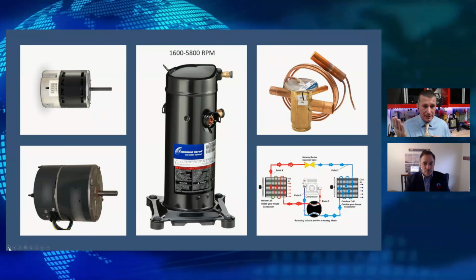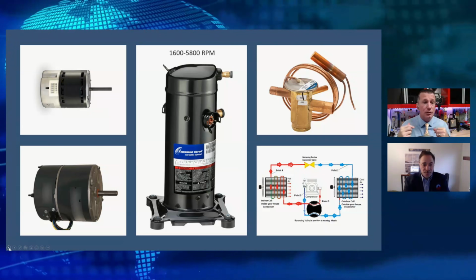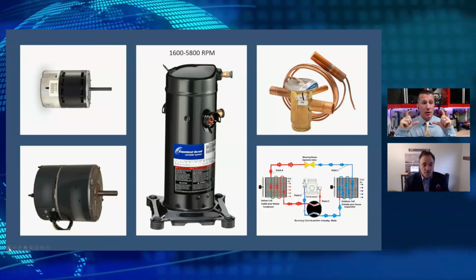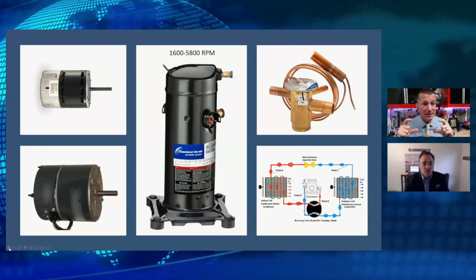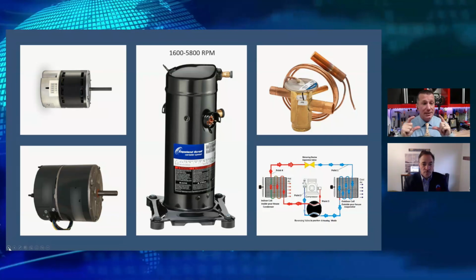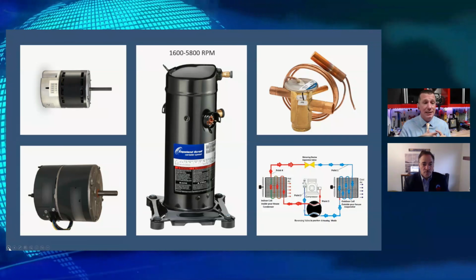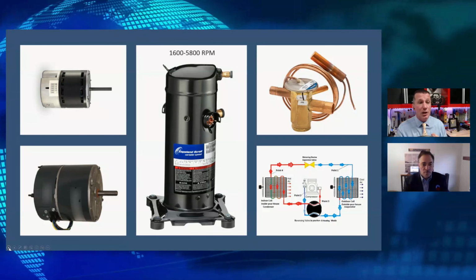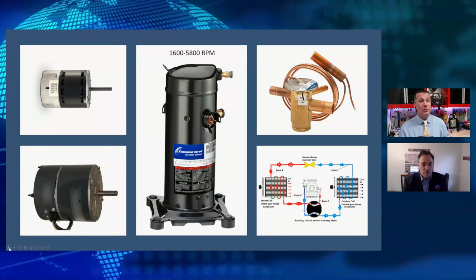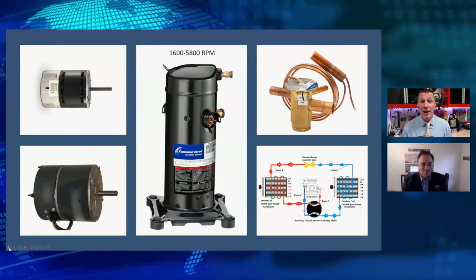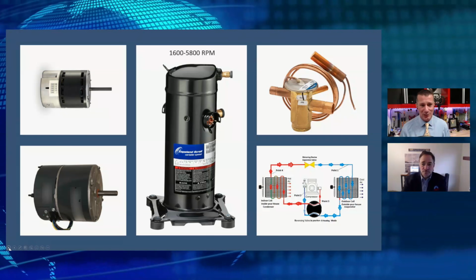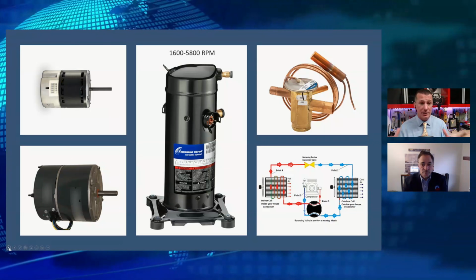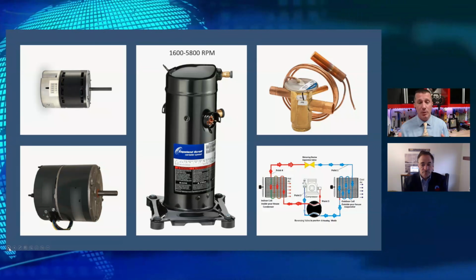They just had different selectable speeds that could be changed from the indoor fan board and from the defrost outdoor board. And then we took the PSC motor out of the compressor, kept our pump inside of the compressor. It took out the PSC, permanent split capacitor motor, and put in a multi-speed ECM. So, is it an inverter? Well, it is able to vary the speed of the compressor. So technically, absolutely, it is an inverter, and it is an electronically commutated motor that is driving the vapor pump.